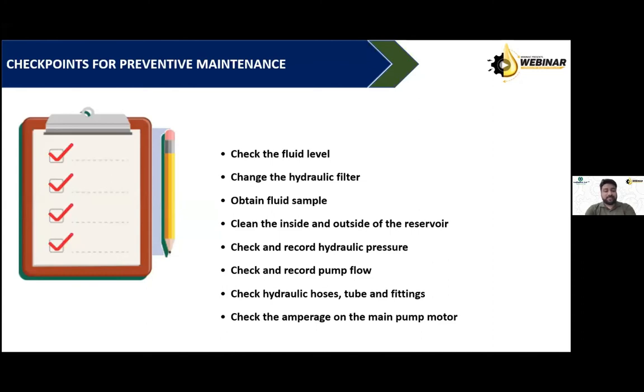Here you need to understand that many times these DP gauges don't function because they themselves get choked. So you have to check whether they are working or not. And if the filters are choked up, you need to change them. Filters are not there to last as long as life goes. Filters are there to be changed, and filters are there to save us. That's why in many countries they call it a monitor and not just a filter, because they are there to check our contamination. And if they have got choked up and you're still using them, then you are just making them redundant and not serving the purpose.